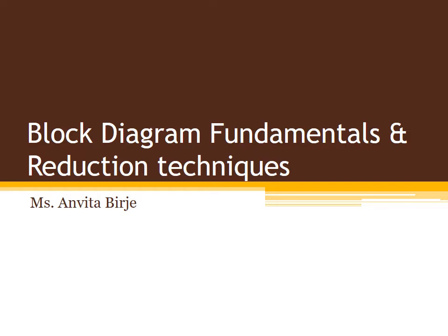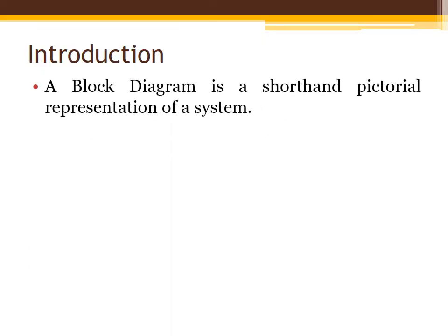Today's video is about block diagram fundamentals and reduction techniques. Analysis of a complicated system is very difficult, so finding the transfer function for that system is also complicated. Basically, a block diagram is used to find the transfer function in an easier way. A block diagram is a shorthand pictorial representation of a system.